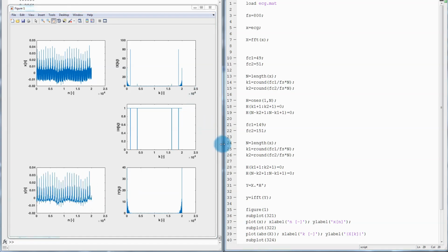There is actually one more concept that is very nicely illustrated on this example. Let's take a look at this spectrum. You can very clearly see the first harmonic of the power noise interference. The spectrum of ECG is slightly more difficult to see. It's very small and you can see it only for low frequencies. You cannot see it for higher frequencies because it is so small that you cannot recognize it from zero. And this is a very common situation.